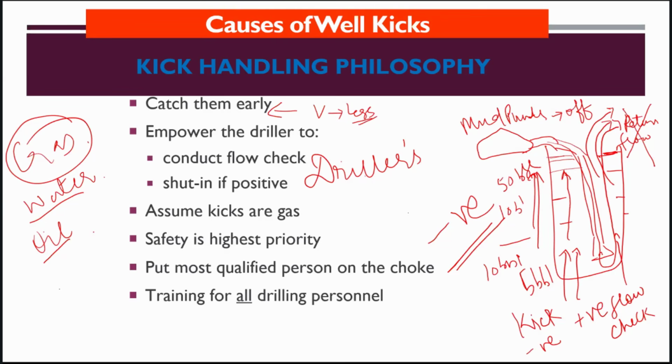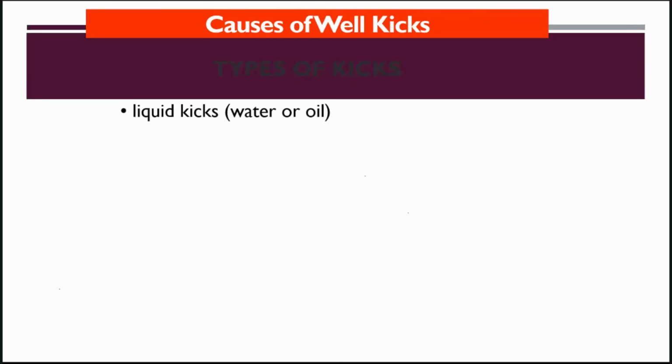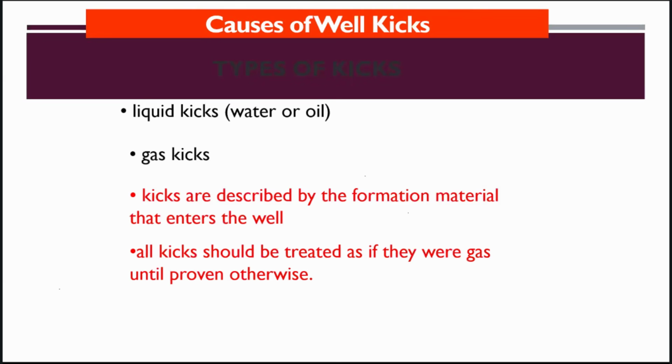And safety is the highest priority as always. Put the most qualified person on the job and train all the drilling persons. Your kick can be liquid or gas, and liquid means water or oil. So unless and until it is confirmed, treat all the influx as gas because it is most dangerous.